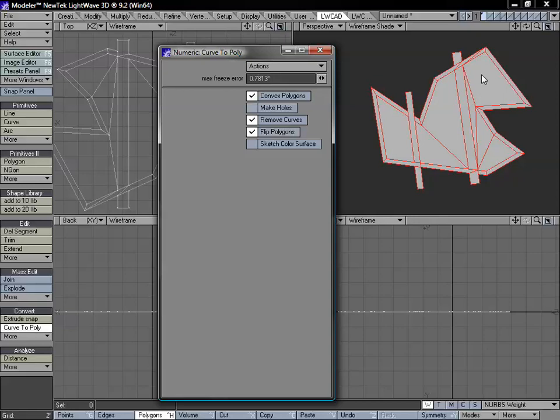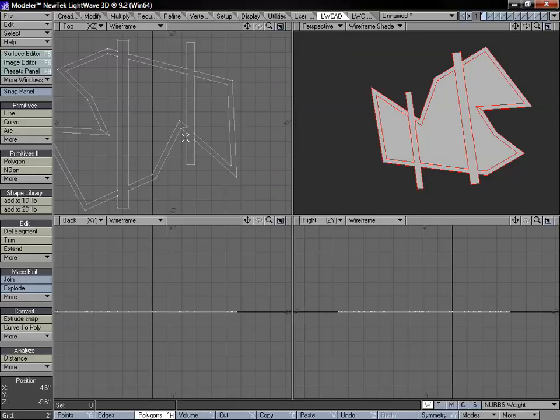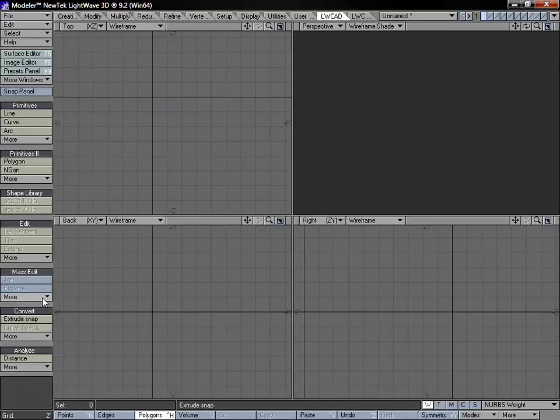And this is also helpful if you're going to be creating offset shapes. And like I said, if you're going to extrude them and keep those top polygons, then you want to make sure that you have convex polygons on, because that will prevent some of your overlapping and some of the errors that you will have without it on. Go ahead and delete that. And now we'll take a look at some of our next options.